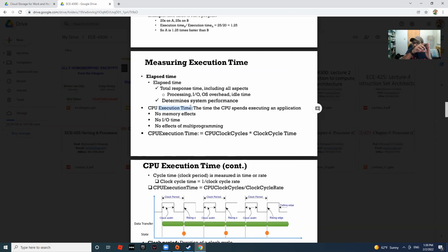How? There is a bunch of sequential and combinational elements in the middle, right? And I know the response time of every single element. You keep adding, accumulating them, you will come up with a number, and this number will be in seconds, nanoseconds, or microseconds. It's a time, right? If you flip it, it will be the maximum frequency, right?